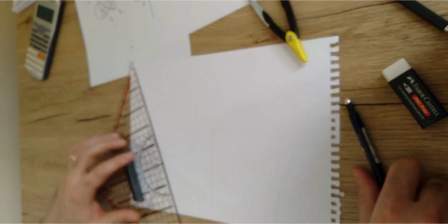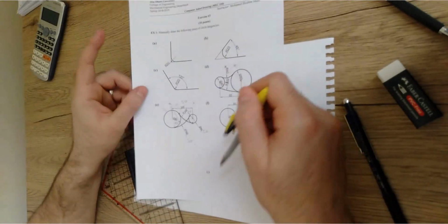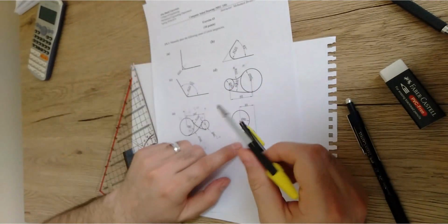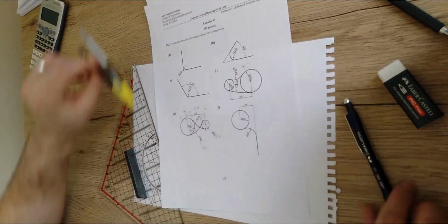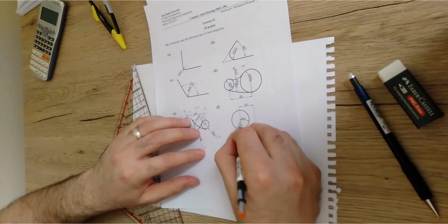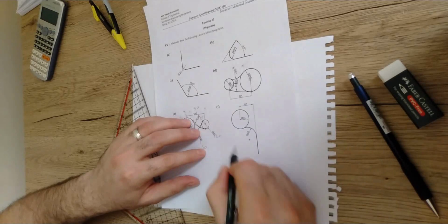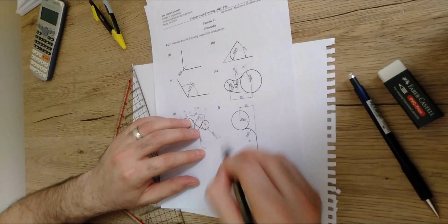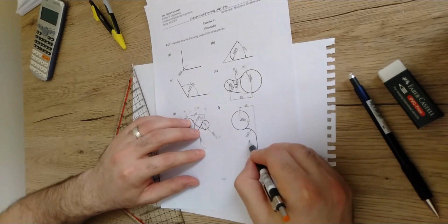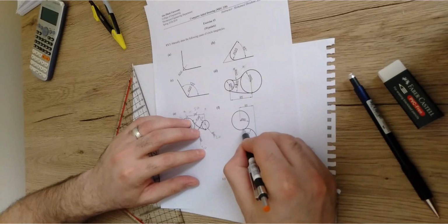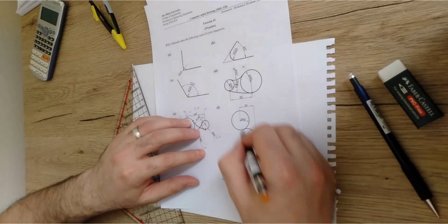How about the second locus, where we're gonna use the other object that this curve is tangent to? It's tangent to this circle. So from the center of this circle to the center of the curve, it should be somewhere in this region, right? And this should be the tangent point. So if I ask you to move from the center to the center, are we gonna go over the tangent point? Yes, we're gonna go over the tangent point.